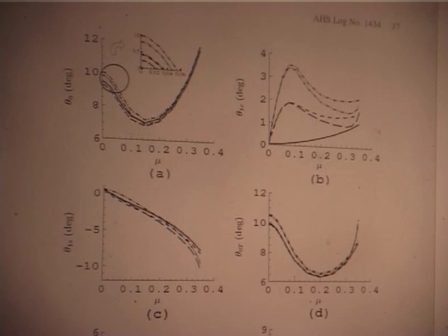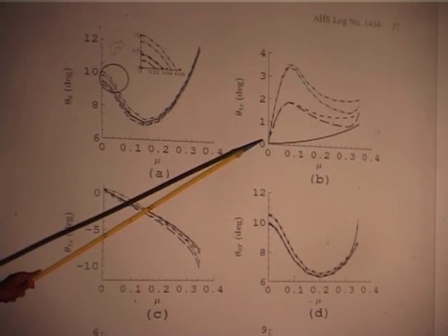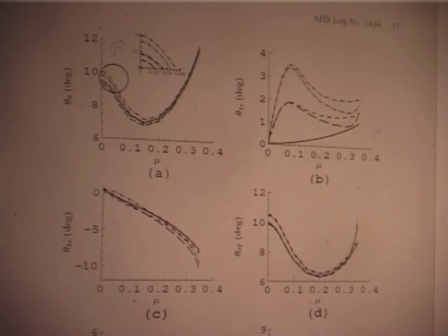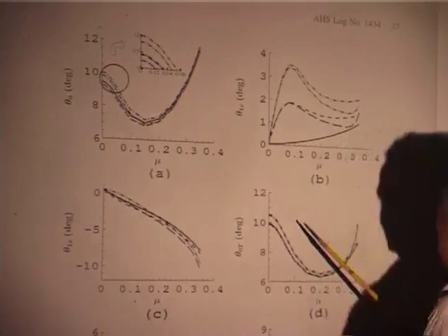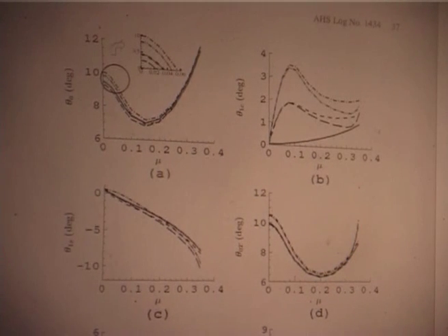You want to go high speed, what do you do? You increase the throttle. It is not that you go to high throttle for low speed and then come to low throttle for high speed. It does not happen that way. But here, this was why it happens. This was a question. A lot of people say, of course, it is due to inflow modeling, but inflow and stall put together gave it, whereas Dries model, which I mentioned to you, gives slightly this result, but we need to have stall also. And of course, the tail rotor follows a similar trend as the main rotor, okay.